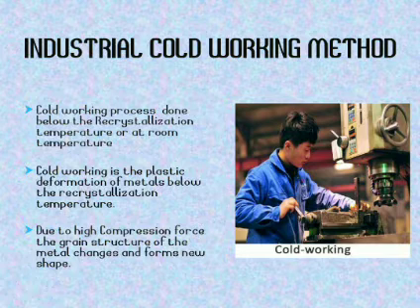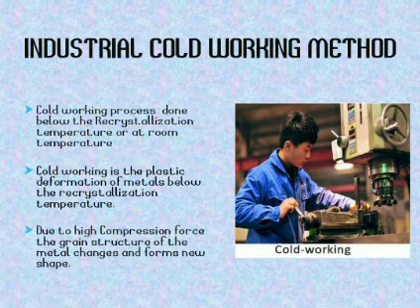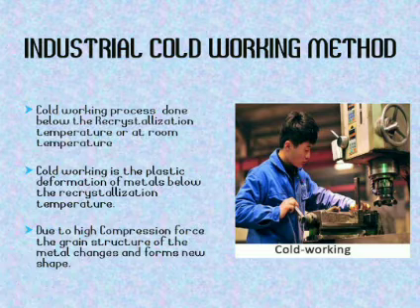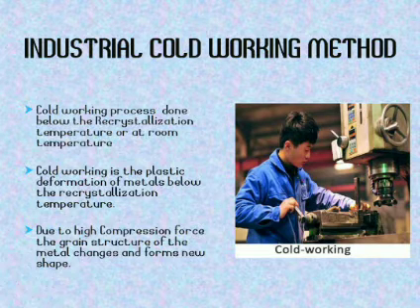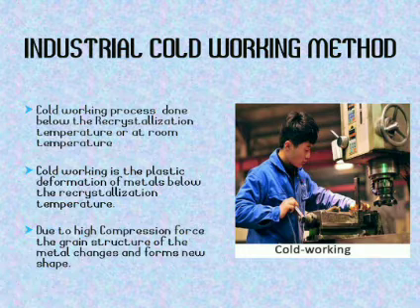So industrial cold working method is a process done below the recrystallization temperature at room temperature. Cold working is the plastic deformation of metals below the recrystallization temperature, and due to high compression force, the grain structure of the metal changes and forms a new shape.